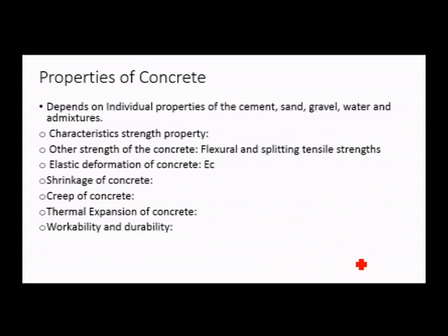There are some properties of concrete depending upon the individual properties of cement, sand, gravel, water and admixture. The characteristic strength is defined as the strength below which not more than 5% of the test results are expected to fall.